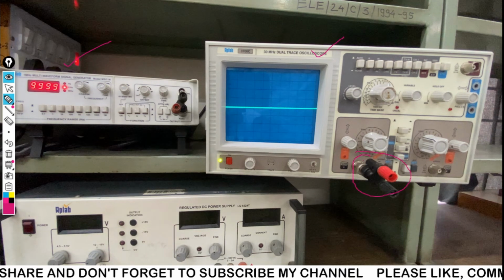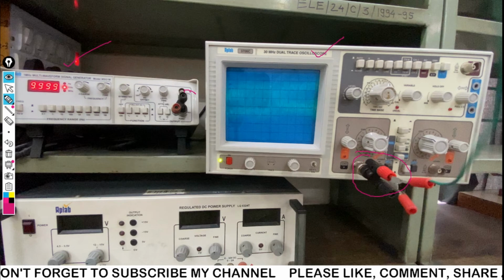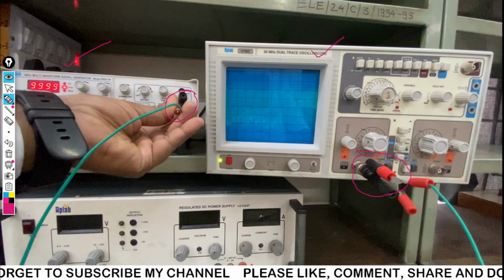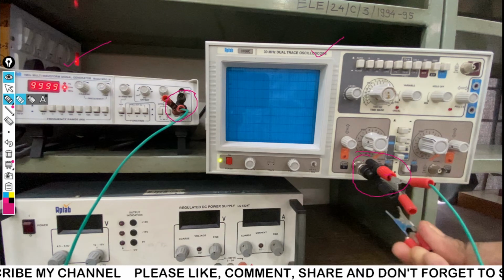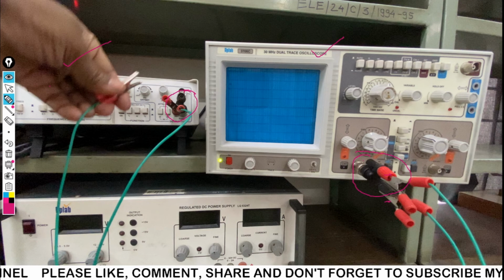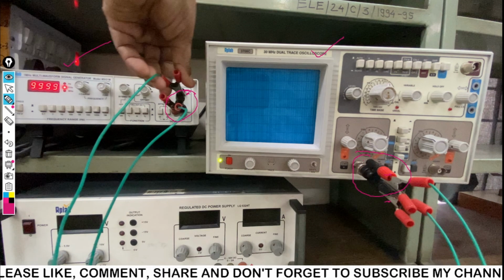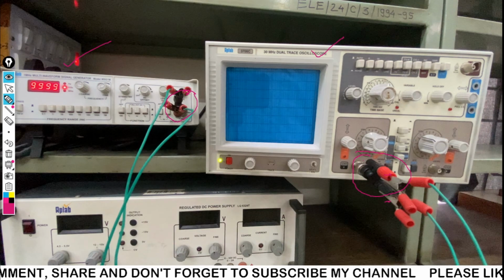Then I require a probe that should be connected at the function terminal or function pin of this signal generator. I'm going to connect the positive with the positive of this function generator, and then the negative wire should be connected to the negative of this signal generator. So you can see here some waveform is shown on this particular CRO.